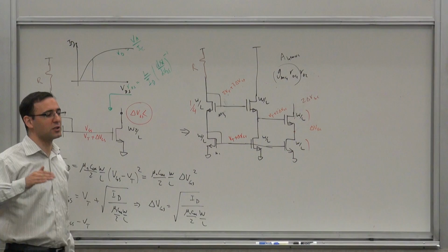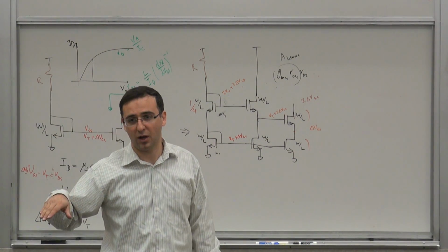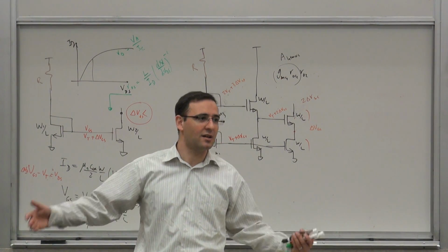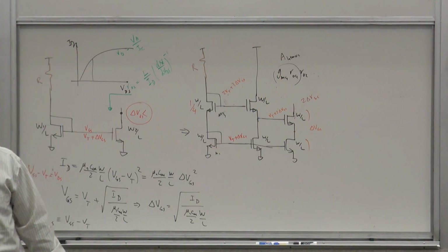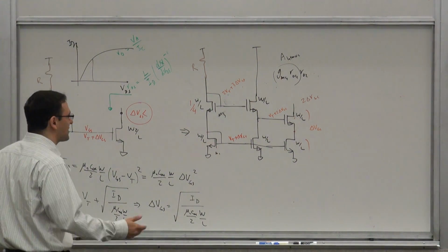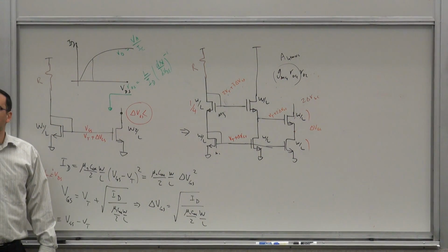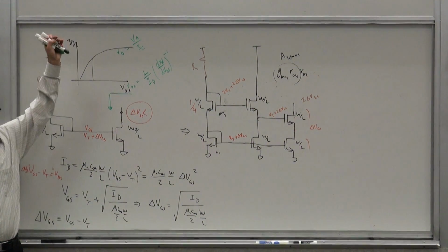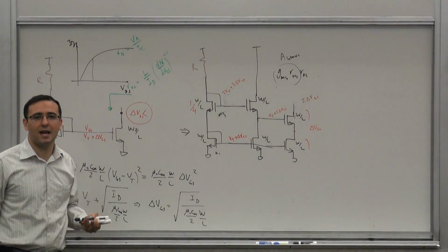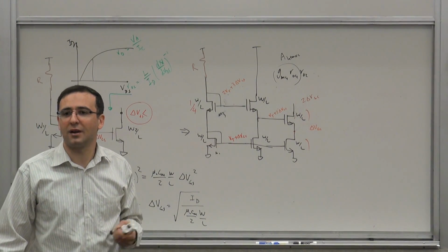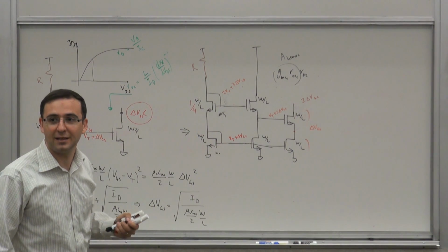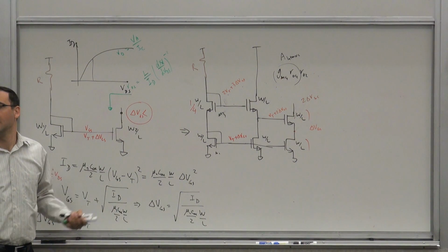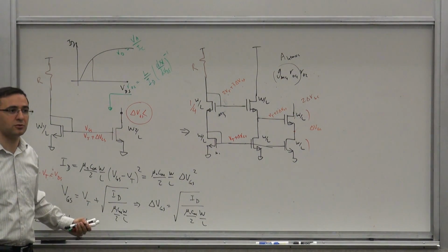If you want to make a voltage, for instance, that's pretty much independent of supply, you can make something that doesn't change that much, very, very small variations in terms of tens of ppms per degree. And there are precision things that even go below that. But you may or may not need it for your design. If you are designing something where the battery is changing over a range of, let's say, 25%, then you can get away with something relatively simple. But if you're making a precision device that will be used to make some very accurate beacon somewhere, to do something special, then you need to do a lot more.